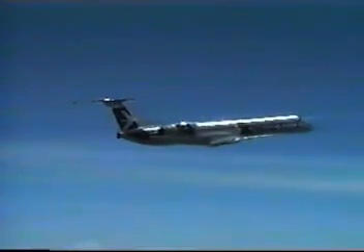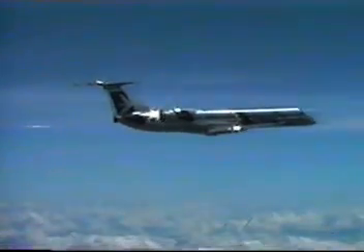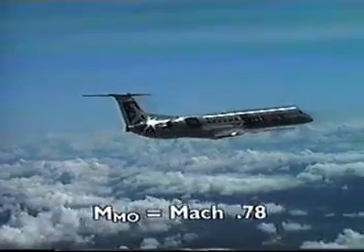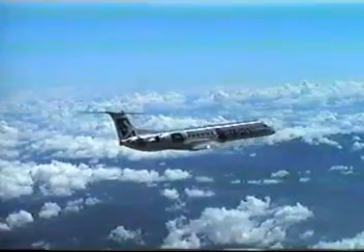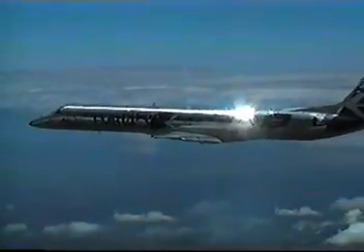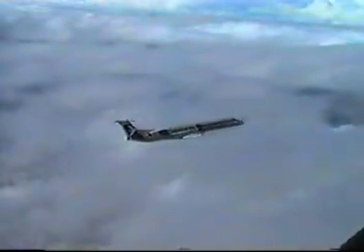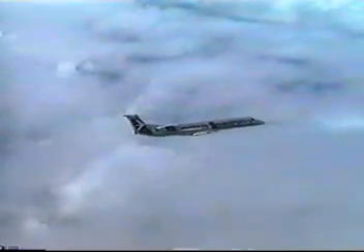The Embraer jet aircraft has been extensively flown to Mach 0.85, and no tendency like the Mach tuck has been observed. Recall the maximum operating speed is Mach 0.78. Embraer does not recommend any flight excursions beyond the aircraft operating envelope. Should an excursion out of the operating envelope develop for some reason, you ought to know that some pitch-down tendency might occur at speeds in the vicinity of Mach 0.85 and over. The mild tendency can be safely counteracted conventionally. That is, pulling the yoke will cause the aircraft to recover.